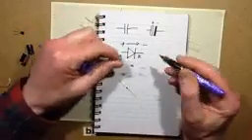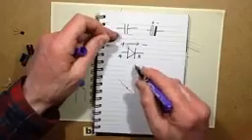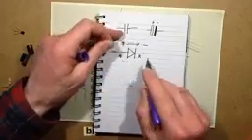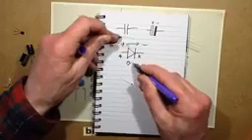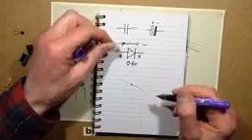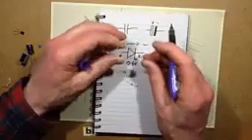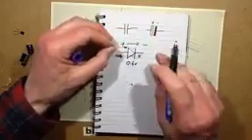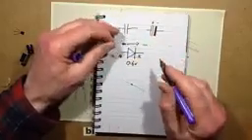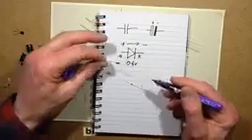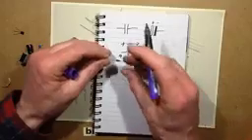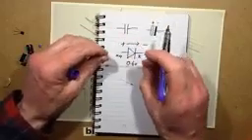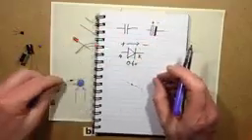This is a silicon diode, which, when it's forward passing current in the correct direction, positive to negative, will typically have a voltage drop of about 0.6 volts. Sometimes, depending on the voltage rating, it'll actually go up to 1 volt, and it also depends on the current flowing through it. You get Schottky diodes, which have a much lower forward voltage of between 0.2 to 0.5 volts, and in cases of rectification, that lower voltage actually makes them much more efficient.